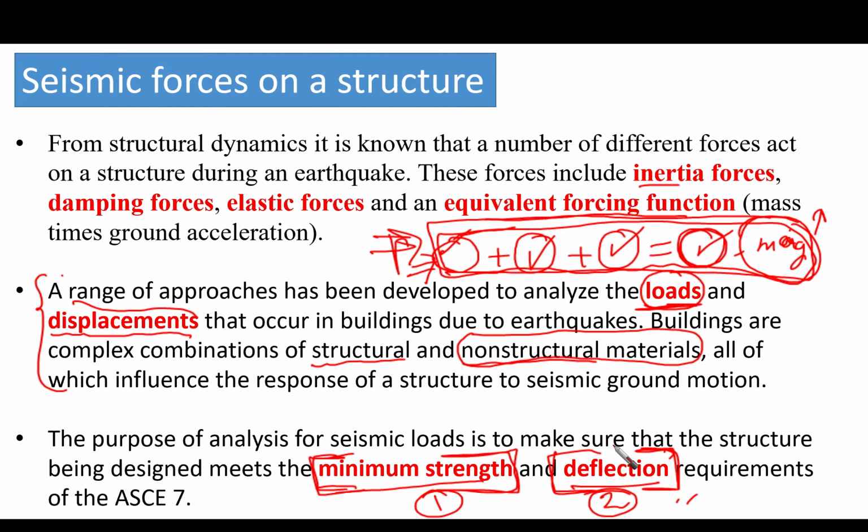So now this is actually considered to be one of the limit states, the strength limit state, but we have other limit states which are not considered here in this code. Maybe we are going to design for different limit states. Here we are talking about a certain limit state, which is the strength, life safety limit state, for example. But we have other limit states like immediate occupancy, life safety, of course, collapse prevention, and so on. The code does not work for other limit states. Only one limit state is working for it.